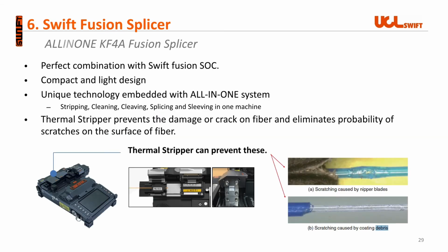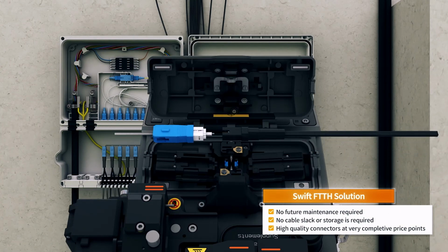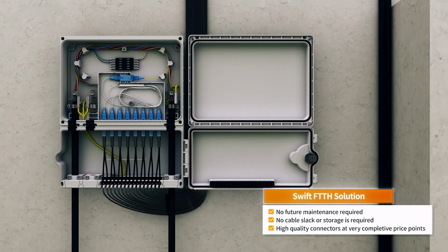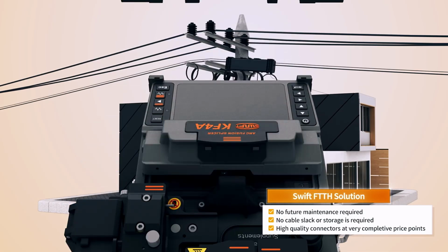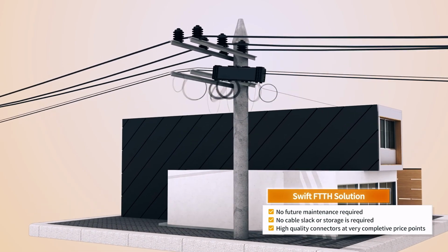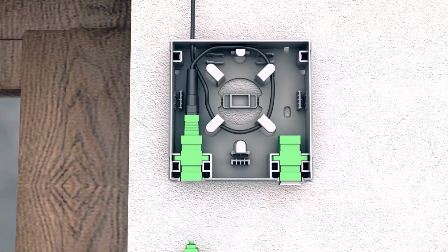The KF4 Fusion Splicer is the best performing and most effective tool for terminating optical cables in the FTTH network. The field installable Fusion Splice-on connector and Hardened Fusion Splice-on connector can be assembled on site in the FTTH last mile, and various types of cables such as 0.9 mm, 2 mm, 3 mm, 2x3 mm drop cables and ruggedized drop cables can be terminated with those connectors.